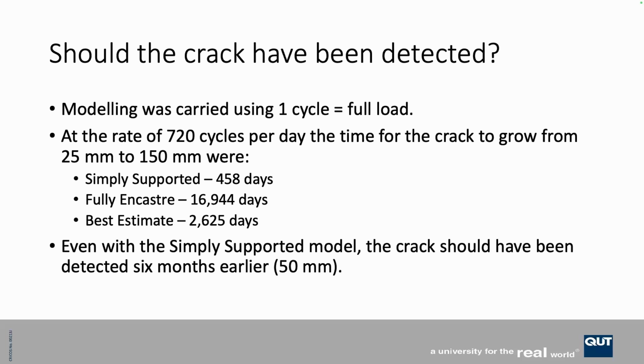Now, the reasoning for 25 millimeters to 150 millimeters is this. I figured that not even the stupidest NDT tech could miss a 25 millimeter deep crack. I shouldn't say stupid. Even the most careless NDT technician should be able to detect a crack that is 25 millimeters deep. And 150 millimeters is the limit of what the equations would work for this particular setup. And I thought any crack that's bigger than 150 millimeters is going to crack really quickly anyway, so it doesn't really matter.